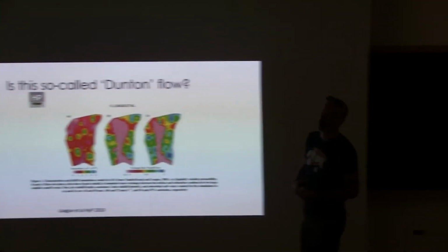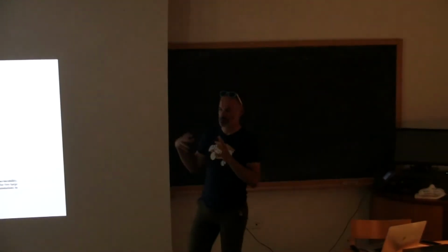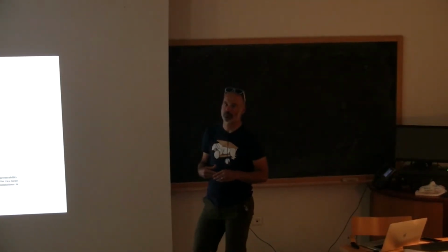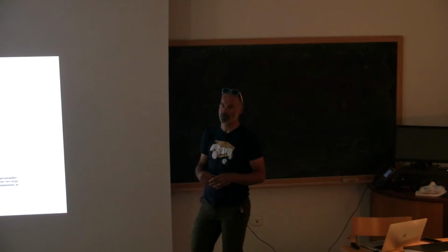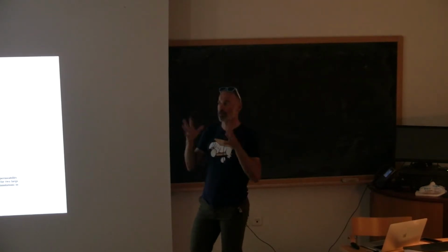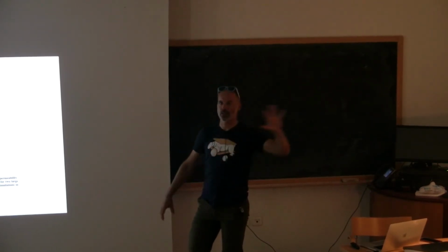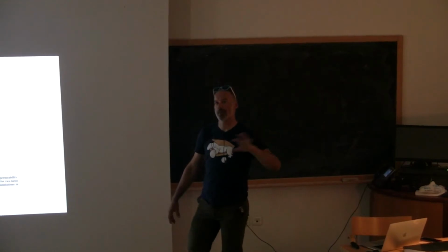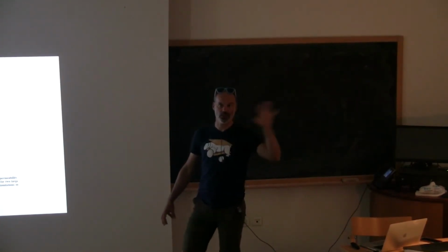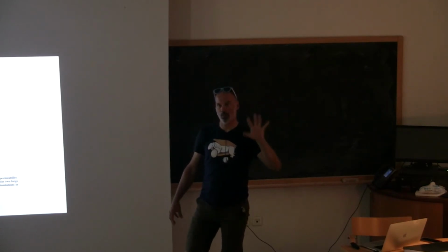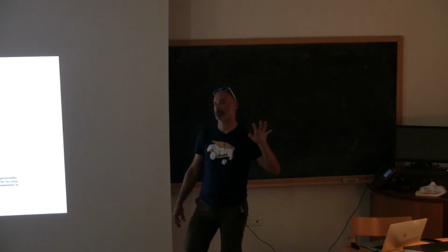And some work that's in review right now from one of my current PhD students, she's actually finding a heavy scale dependence of effective hydraulic conductivity. I tend to think of it as there is, at some fine scale, a representation of the hydraulic conductivity that is fixed. But we're almost never working at that scale.